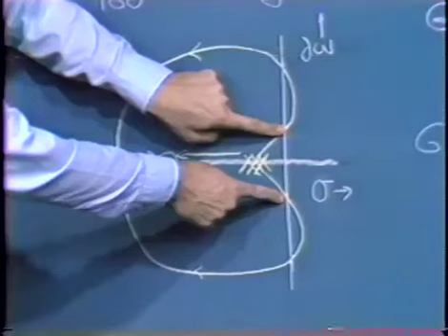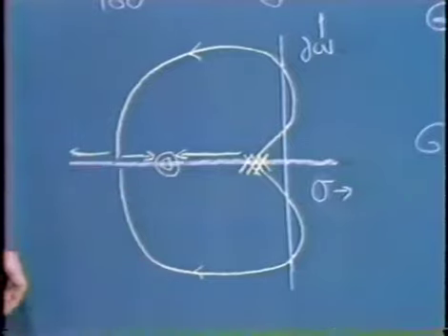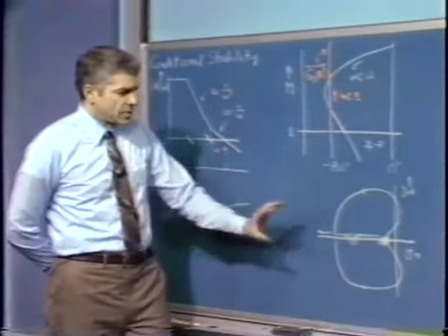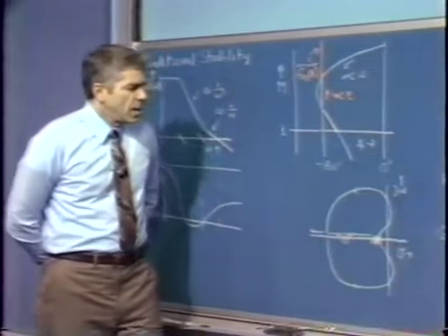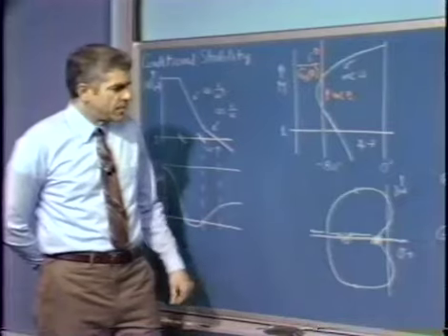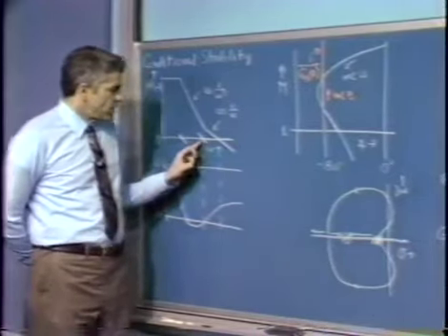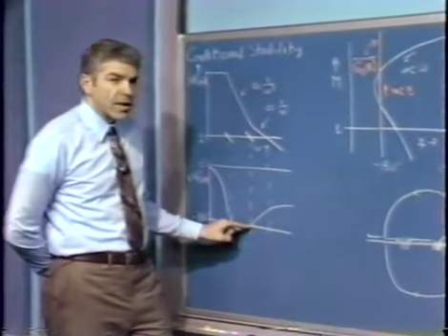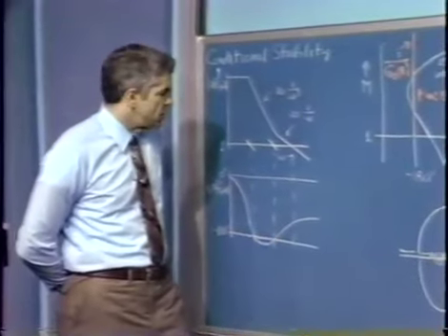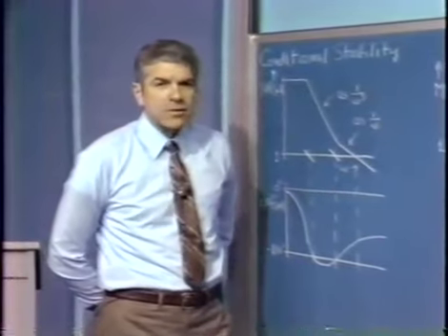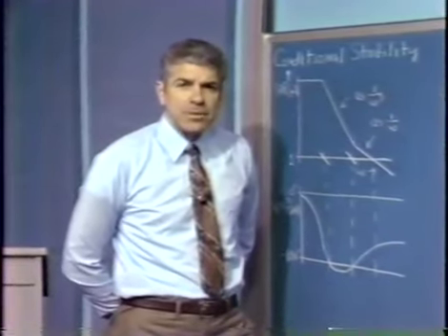We might end up at this point. That's, again, a borderline stability point. Well, we see either from the classical describing function analysis, or from the root-locus analysis, that there are two values of E that result in a system that has unity magnitude for the loop transmission at the frequency where the angle associated with the AF product is minus 180 degrees. And we have to consider which of those, if either of those, represents a stable amplitude oscillation.